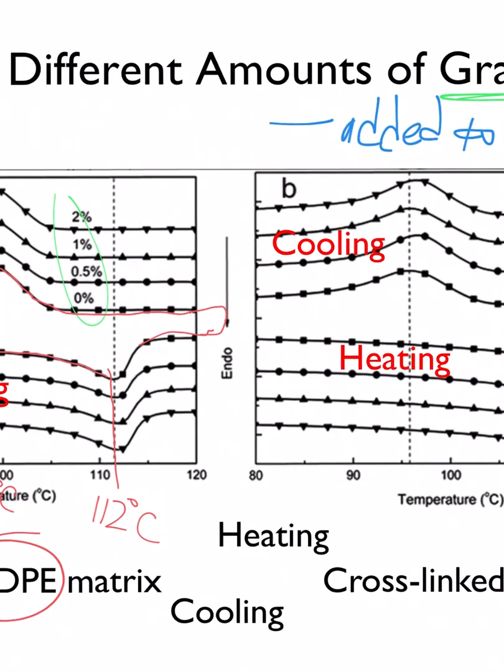So you can do this with regular polyethylene, you can do this with low-density polyethylene, you can do this with polypropylene, you can pretty much do it with anything. You hit it with enough X-rays or gamma rays or electrons, and you cause cross-linking to occur in these systems. And so once you've done that for this particular form of LDPE, we'll track it again. So now, in the presence of these cross-links, this transition, instead of being 112, is, I don't know, maybe 113 degrees C, something like that. So it shifts upwards a little bit.